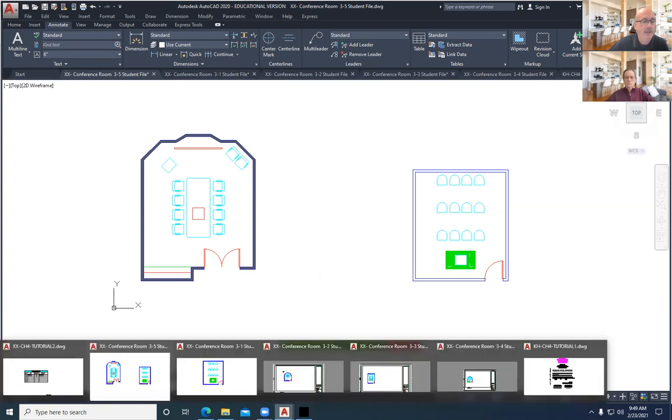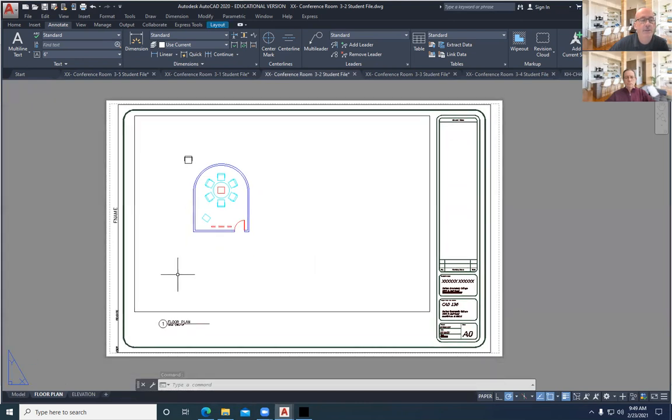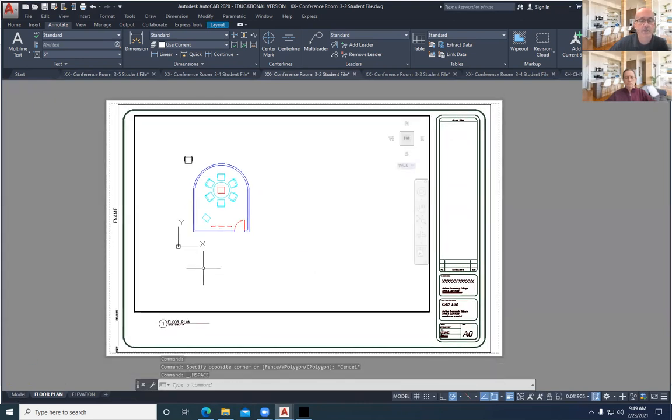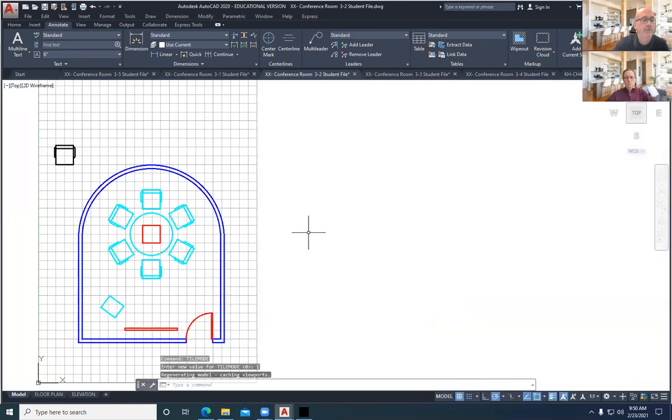And then if I come back and get another drawing from here, I'm going to go to model space. You can work in the viewports. If I double click here, this is what's called floating model space. And the command for it is called TILEMODE. When you designate it as 0 or 1, it will go between model space and paper space.